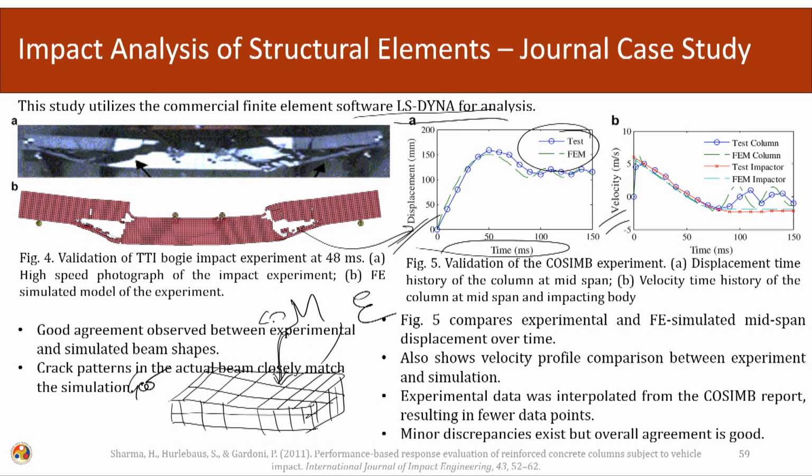For the material, if we are using an elastic material, say steel, we will need the value of the density of the steel, the value of E of the steel, and the nu of steel. The mass density of the steel is 7850 kg per cubic meter, E is 210 GPa and nu equals, let us say, 0.3. Using these three values we can define the material as elastic steel material. The element formulation we can use as constant solid formulation.